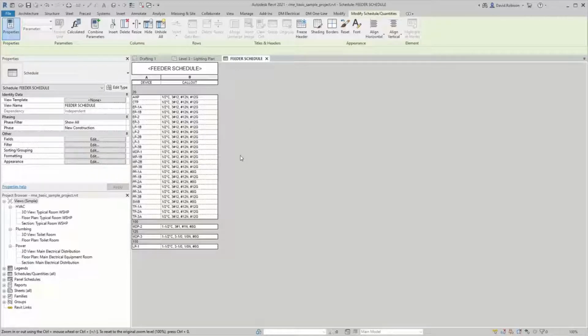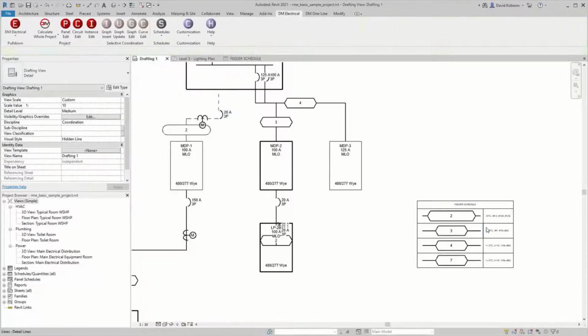If you have electrical equipment, you can't have all of the branch circuit devices, your mechanical equipment, your elevators. It's really hard to get them on the same schedule as your panels using a Revit schedule, because Revit sees them as very different, and they kind of are, but in terms of their feeders, they're the same. And so Revit's just like, I don't know what to do. So that's why we did our own feeder schedule.